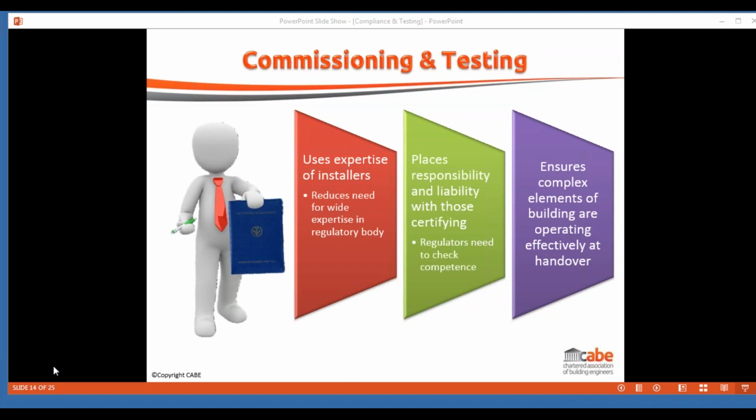And it does mean that very quickly after the building's completed, if something changes, such as a window seal is damaged, the actual performance in use is still going to be significantly different from the test result. And those of you who've witnessed testing, particularly for things like air tightness, will see that during the test certain parts of the construction, like the openable background vents and things like that, can actually be sealed. So again, it doesn't necessarily reflect how the building is going to work in use. It's more of a comparison.